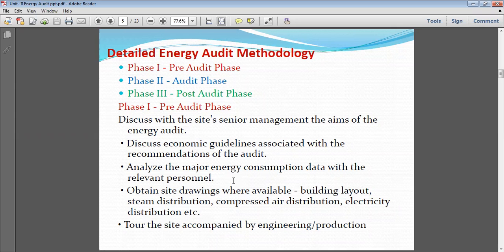By a small modification in the pipeline, we can definitely save energy and improve the efficiency of the pumps, because by doing such activity we can decrease the static head and decrease leakages in the systems, isn't it? Therefore the distribution layout is very necessary for doing the energy audit program.